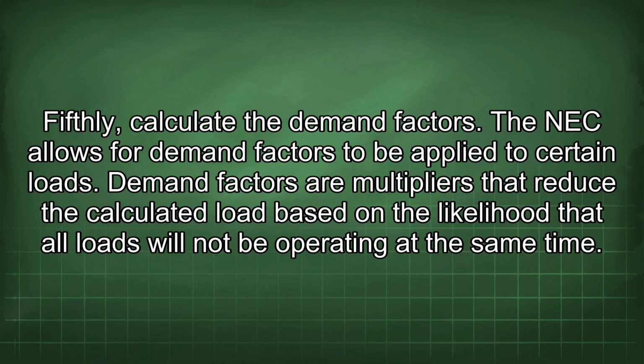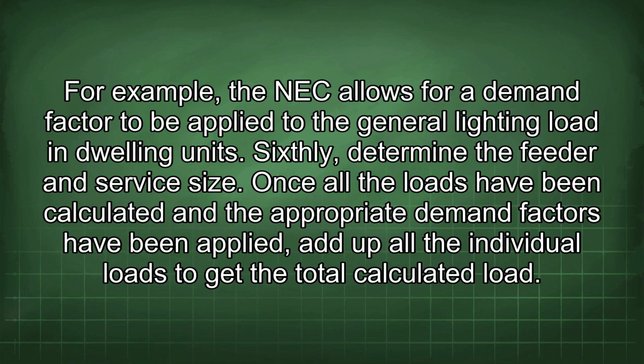Fifthly, calculate the demand factors. The NEC allows for demand factors to be applied to certain loads. Demand factors are multipliers that reduce the calculated load based on the likelihood that all loads will not be operating at the same time. For example, the NEC allows for a demand factor to be applied to the general lighting load in dwelling units.